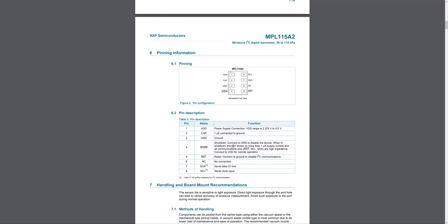So that's kind of an important pin we could play with, because that would enable us to, if you're talking about wanting to make sure you don't do battery drains for an actual real application, we can shut this down, because if you think about 1 microamp, even at 5 volts, or 5.5, 1 microamp would be 5.5 microwatts, so it's not going to be consuming a lot of power in the shutdown mode.